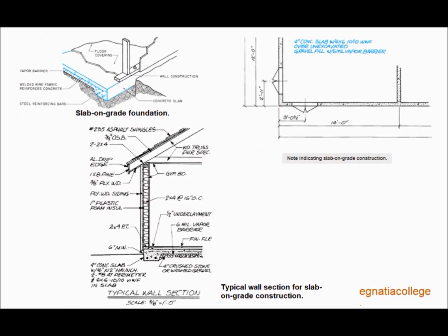All soil changes shape under force. When the tremendous weight of a building is placed on soil, the soil tends to compress under the foundation walls and allow the building to settle. To prevent settling, concrete footings are used to spread the weight of the building over more area. The footings distribute the weight of the building so that there is less force per square foot of area.